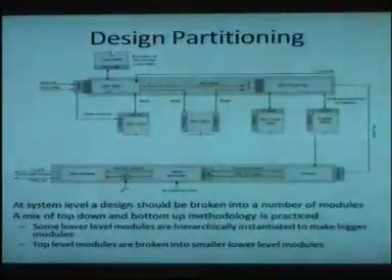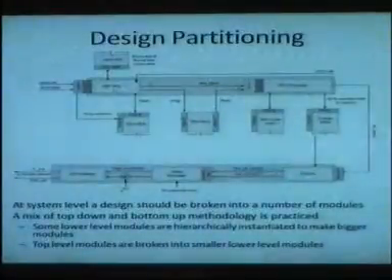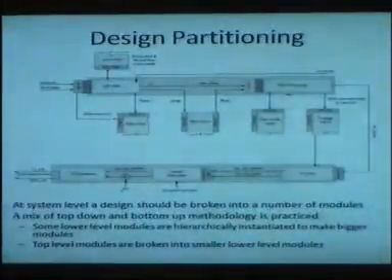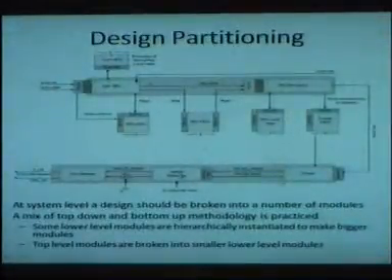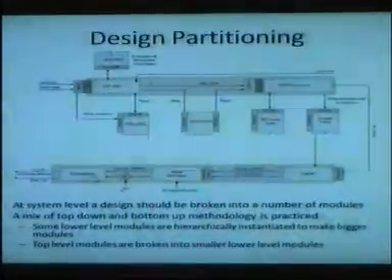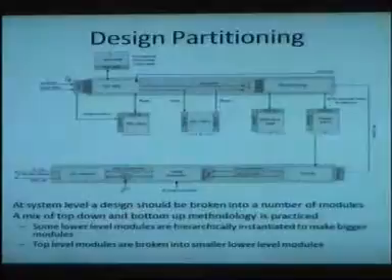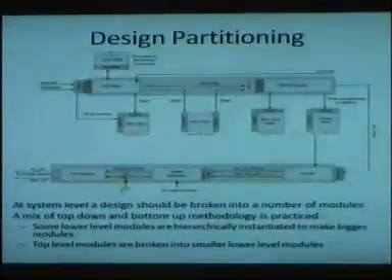So the very first block was the encryption block. We do encryption on this, and once encryption is done, we do forward error correction encoding. When encoding is done, we do the framing. Once framing is done, we do the actual modulation, multiplying it with an exponential, and then passing it to a D2A converter. So this is how a typical design in hardware is done: there are blocks.